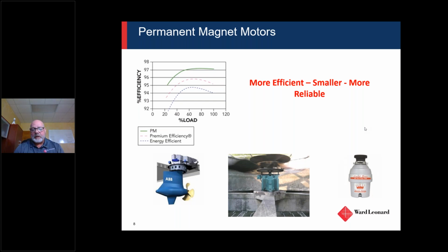It's expensive in materials, right? Because rare earth magnets are expensive to construct, they're hard to get a hold of, and then if you have to maintain them after that, like if we had to do any replacement of the magnets, that gets really, really expensive. So that's why you don't see them applied all throughout the industry, right? It just doesn't make a whole lot of sense where you can plug in a standard induction type of motor, squirrel cage, if you will, and the cost benefit there, even if it did fail, it probably outweighs what the initial cost of a permanent magnet motor would be.